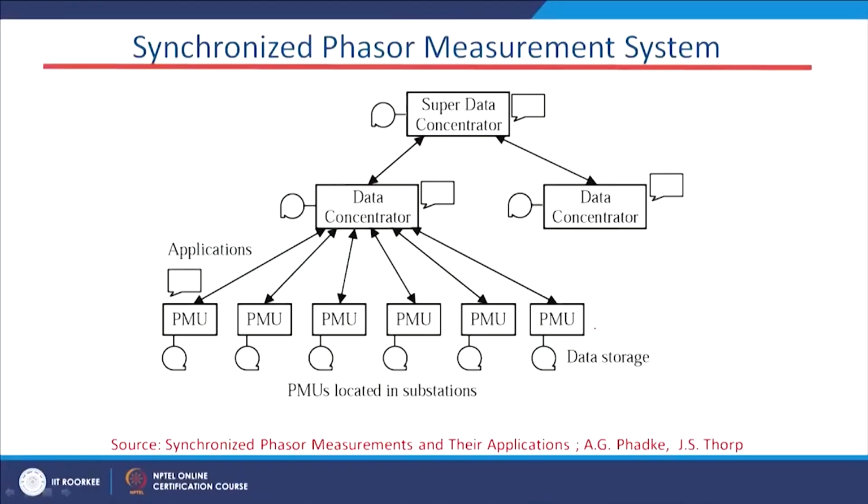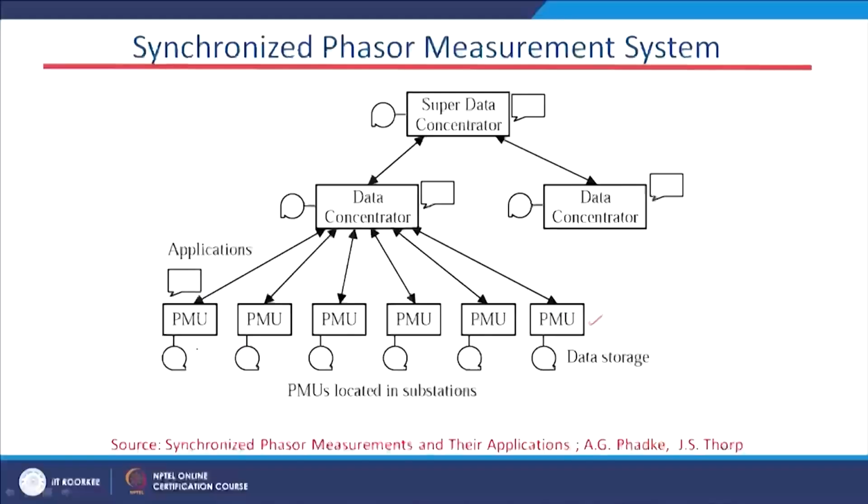First, at different buses of the power network, the PMUs are mostly placed optimally to save cost. We cannot place PMUs wherever we like, because at every bus we cannot put one PMU; we have to put the PMUs optimally. So, we place the PMUs at critical points where we will have complete observability of the system, or complete control of the voltage, current, and frequency signals, where we can measure the voltage and current properly.